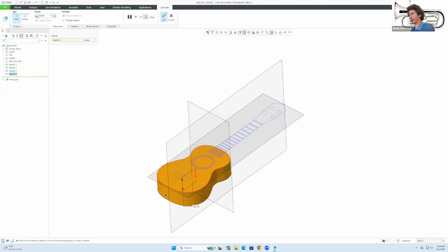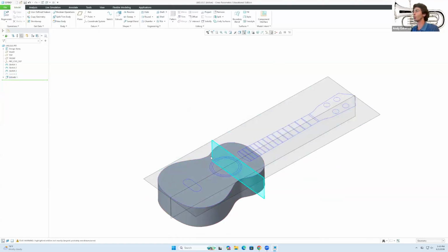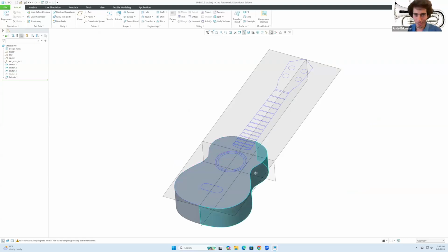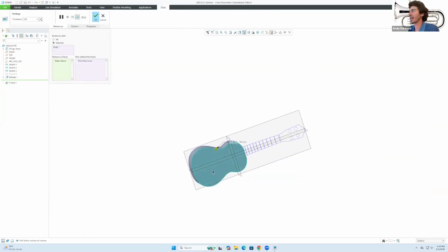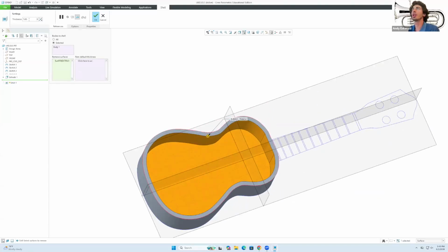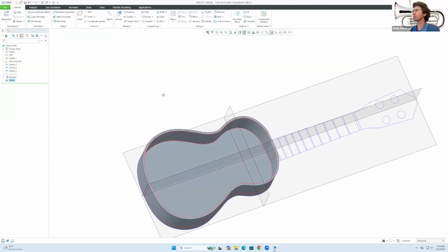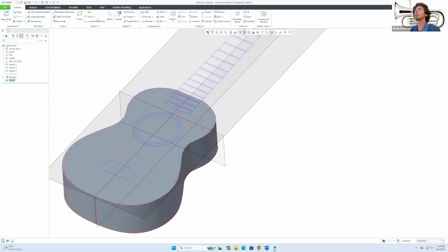No, what, 45, I think that's gonna be the perfect amount. I say okay, good. We can do better than this. I'm gonna go over to where it says shell. I'll select this face in here, and we're gonna immediately shell this out by 3. Let's see how that would look. I think that's fine. Honestly, this looks pretty good.